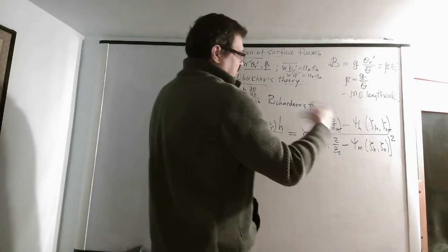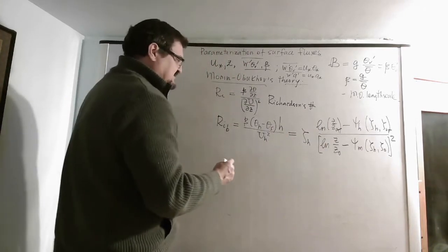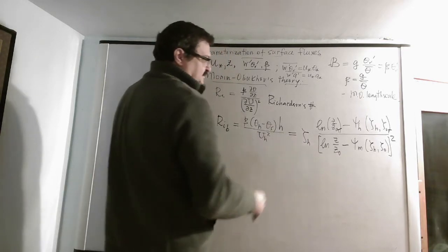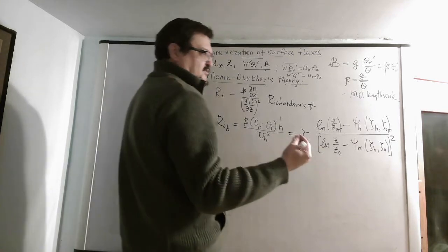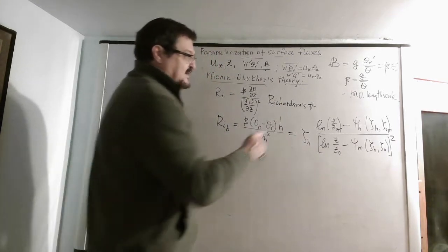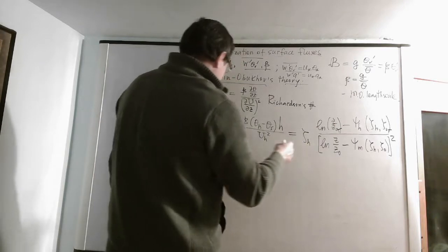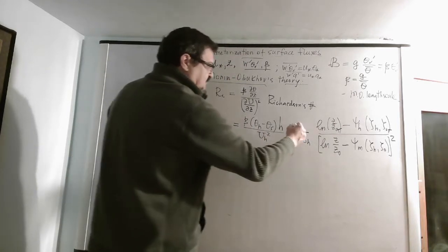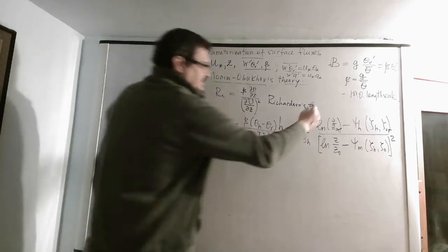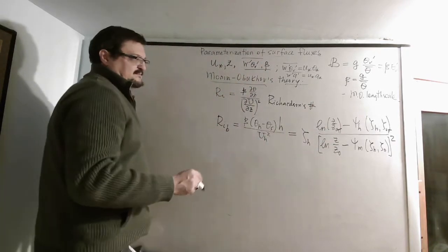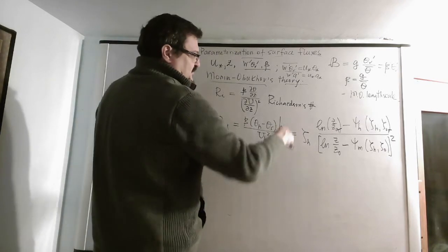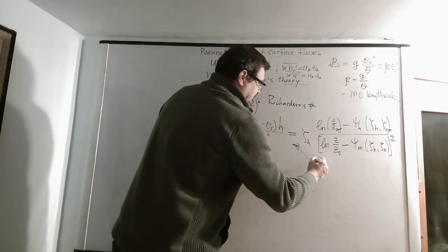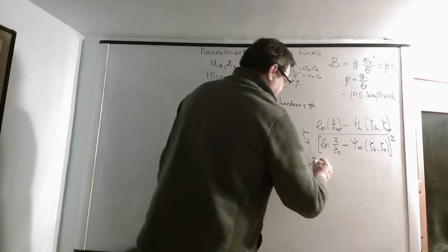So you take your first value of eta as your first guess, let's say from the previous time step, and you substitute it in this formula and compute these terms. Then you write that eta equals the Richardson number divided by all this, and this is your new iteration. Anyway, you solve this by your favorite iterative procedure.